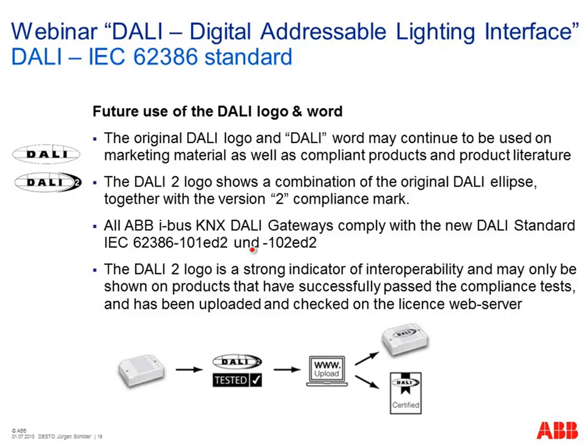Our DALI KNX gateways are already in compliance with the basic requirements of DALI 2, Part 101 and 102. We fulfill this already, but we should be careful. This does not mean that with all our DALI KNX gateways we can work together with any future components which are in compliance with DALI 2. That's not the topic. At the moment we can only be in compliance with these basic functions, general requirements of the DALI standard.